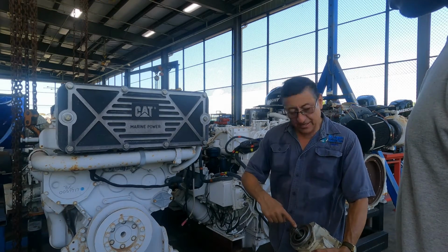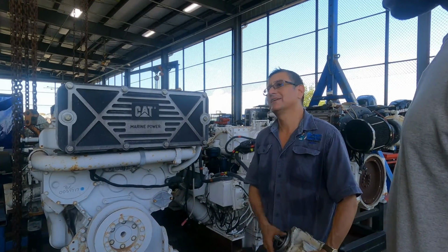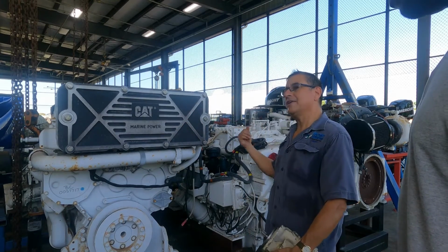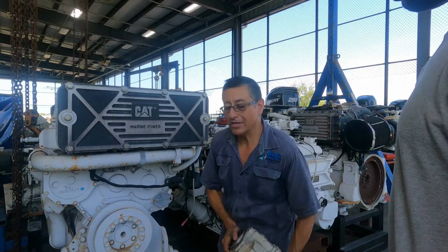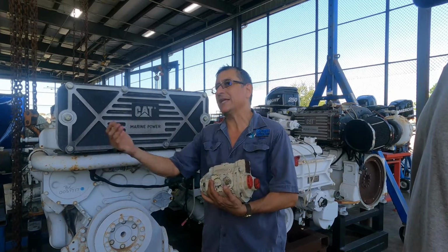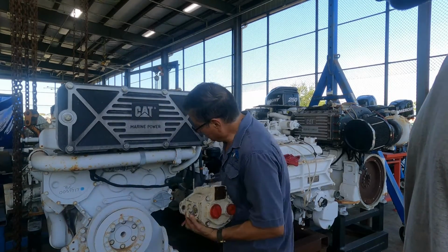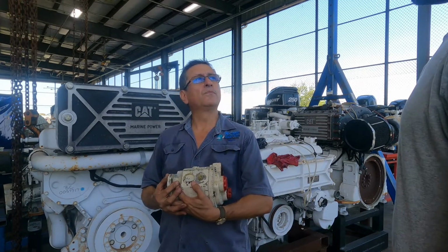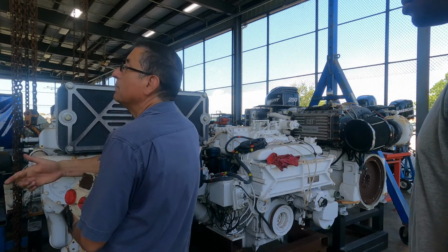And this gear is engaged with the other train of gears. Right now the pump is running with this engine, or with the other engine, this generator or the other generator. The PTO is engaged here with the main engine or with a generator. Where does it go? That one enters here. I remove the plate and engage with it. That's the PTO. Can you have more than one input and one output? No, this is one input and one output.